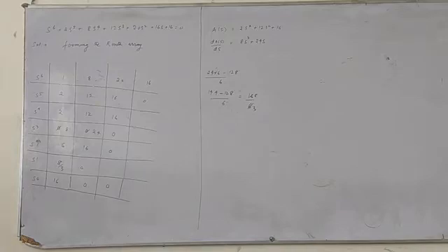The coefficients 8 and 24 are replaced in the row of zeros, in the s cube row of the original tabulation. Thus, the calculation of the Routh array is formed in the usual manner. So this is about the row of zeros.